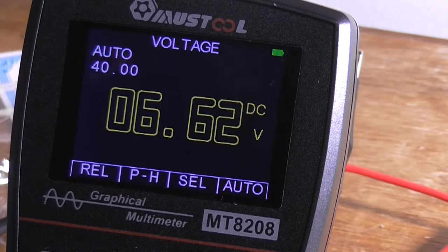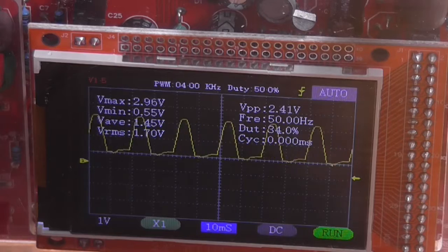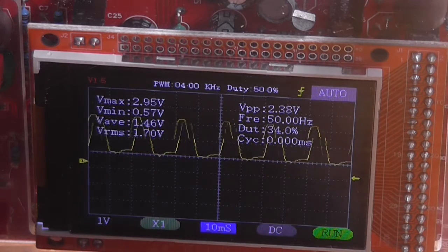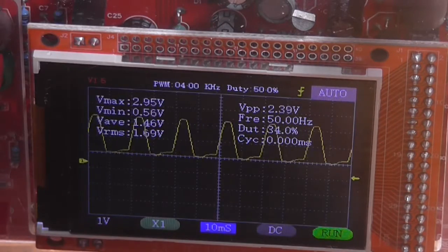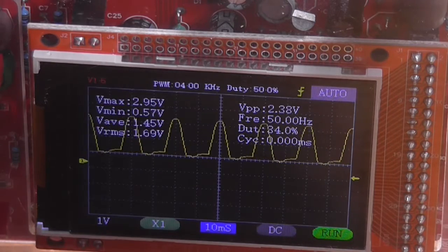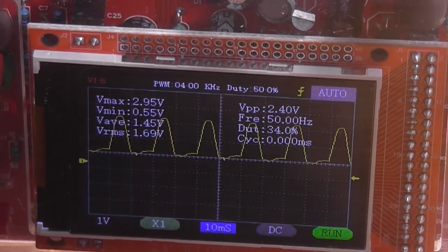Now I'm across a 15 volt winding of that transformer. Why are we only getting 6.5 volt out? Well, that's because this is half-wave rectification, and that's exactly what it does. We're only getting half the voltage because we're missing half the waveform, in a sense. And speaking of waveforms, that's exactly what I described would happen on the output of the oscilloscope. We're only seeing the positive going peaks of that waveform, and the negative going half cycle is missing, which is exactly what we expect, even though the trace is moving across the screen because it's not triggered correctly.